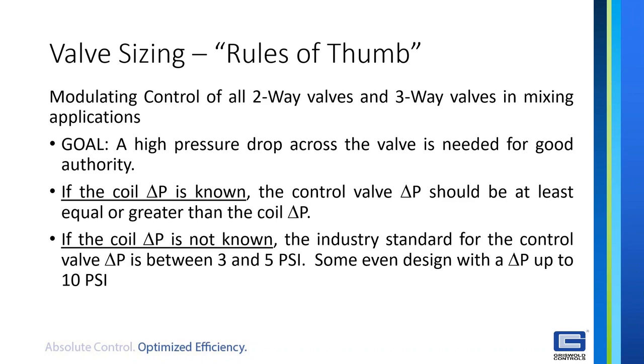That's kind of the rule of thumb, that you want it to be 40%, because if you think about it, what is controlling the flow in a reduced load position? It's going to be whatever is the highest pressure drop. So if the flow limiting valve is the highest pressure drop, it is going to control the flow, and that modulating valve is not going to do anything.